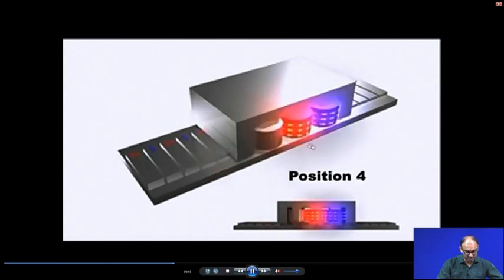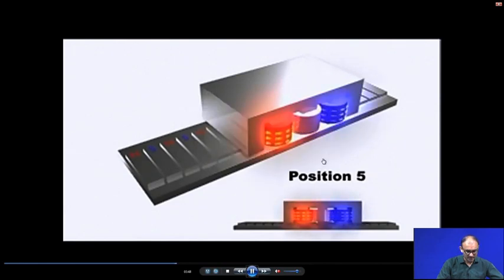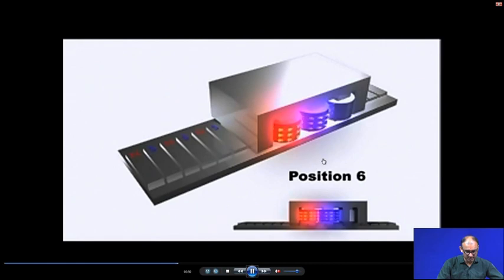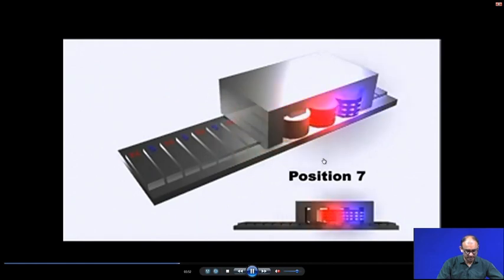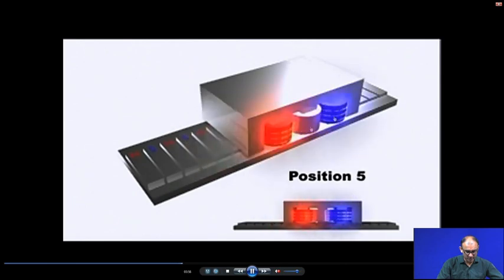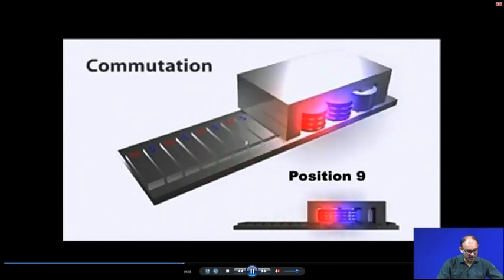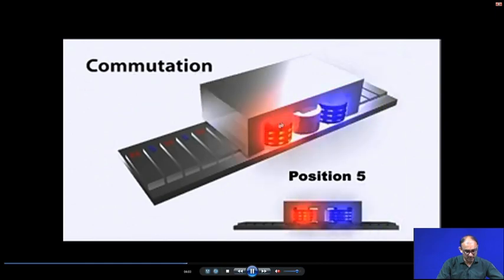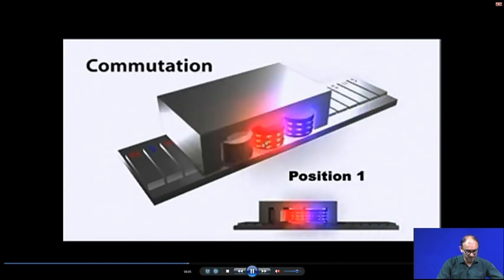So, this is the third position, this is the fourth position, and again the same thing will repeat. First the first two will energize, then the first and the last one will energize, and then the middle one and the last one will energize, correct. This way you can get the linear movement. Now if you increase that frequency of change, then you can get very high speed. This is the commutation, which is how frequently you are changing the current direction.